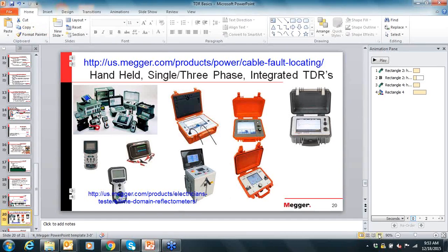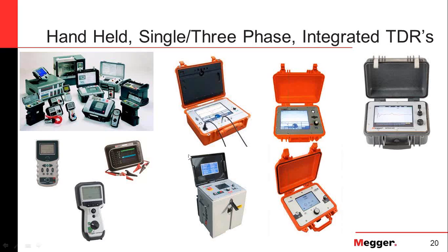That's a good question. For secondary cable, if it has a shield, if it has a concentric, which is not very common, but there are some secondary cables like that, you definitely can use the thumper. We offer thumpers that are restricted in their voltage range that might be used in a mine environment or something like that. But if you're talking about typical triplex secondary cables, you would not use the thumper.